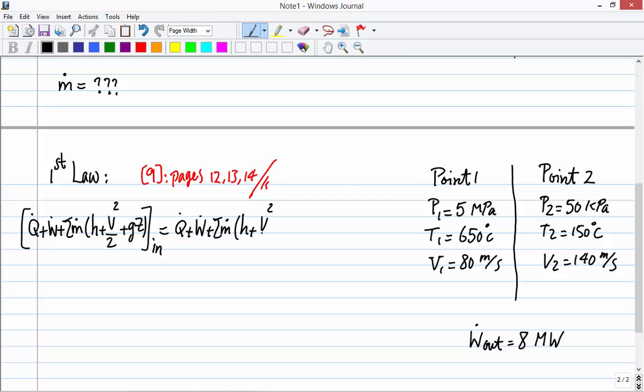And you might ask, why are you using the enthalpy version? That's a great question, and I'm sure you're asking it now. Let me tell you why. Because here we're dealing with a flow, and a flow has flow work. We know that enthalpy H equals U, the internal energy, plus PV, which is the flow work. Therefore, by including H in our formulation, we indirectly include the effect of flow work, right? That's why I'm not using U.